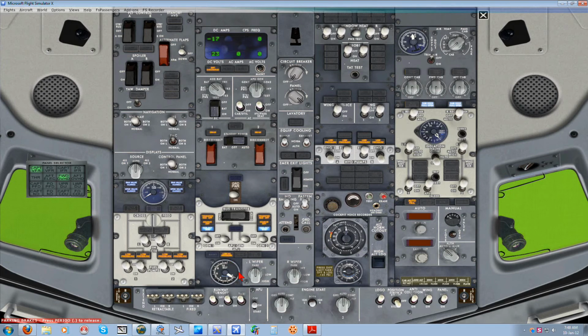So what we do now is we just have to wait for the exhaust gas temperature to come up, which is this gauge here. The exhaust gas temperature will come up to about 9, and then it will level back to about 4. And once that happens, we will then be looking for a blue available light on the APU generator switches. So as you can see here, we've got blue lights above the engine generator switches. So that just tells us that they're available.